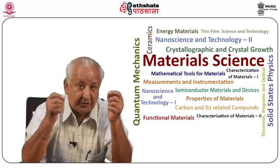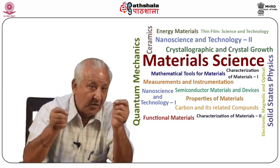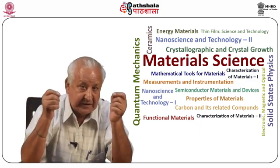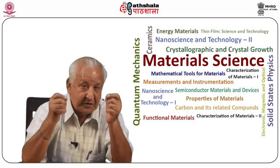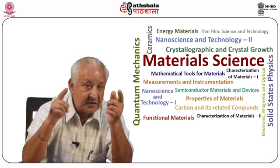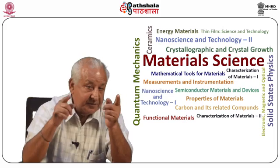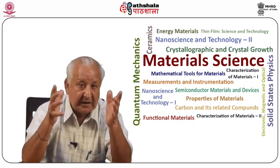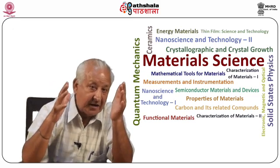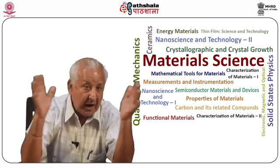It is also used for the growth of very pure crystals, mostly metals, but on a small scale, just for research purposes. Because of radio frequency heating, the surface of the molten zone is heated and the liquid near the melt vapor surface is hotter than elsewhere. As a result, fluid flow is produced. The shapes of the solid liquid surfaces are controlled by these flows and the rate of movement of the zone. The technique does not require any crucible.